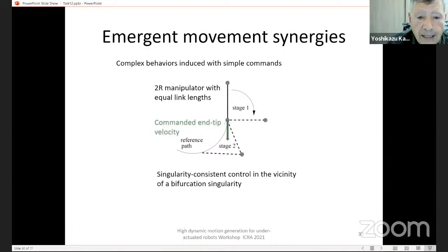So there is no way the robot knows how to move. It stays like this. But if you have a small deviation from the perfect, let's say 180 degrees in the second joint, even an infinitely small deviation, then we know that the system will start moving either right or left. In my case, it's right.